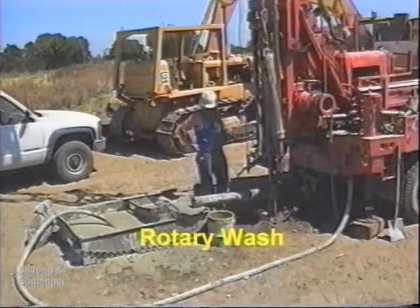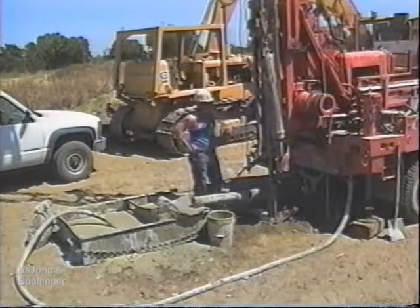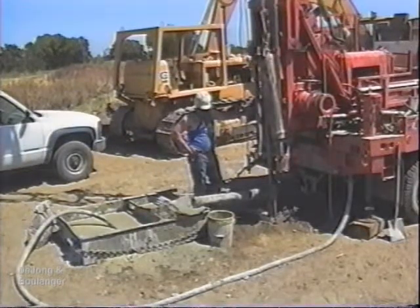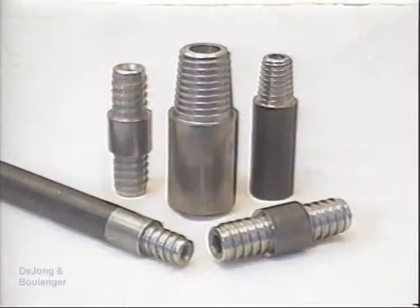Mud rotary, or rotary wash drilling, is very different from the continuous flight auger methods. The underlying principle is that mud, a mixture of water and bentonite, circulates through the borehole, bringing the soil cuttings to the surface and supporting the sides of the borehole. For drilling, a bit is connected to a series of drill rods that are attached to the drill head. Drill rods typically have an outside diameter of 1 5/16 inches to 3 1/2 inches and are attached together using connectors like the ones shown here.